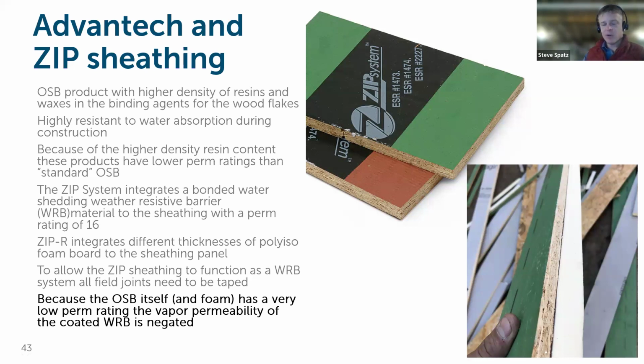That green coating that they put on it as the WRB actually has a pretty high perm rating, but the substrate that it's bonded to, which is the OSB, does not. So this is a low permeability sheathing material. Doesn't mean it's bad, doesn't mean there's a reason you shouldn't use it. And the Advantech is actually even less permeable. But what that means is that as you look at the different control layers behind that, insulation material options, and vapor control, you need to make sure that assembly has drying capacity to the inside, because this type of material is not going to give you a lot of options for outward drying.